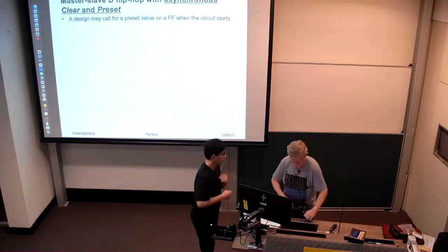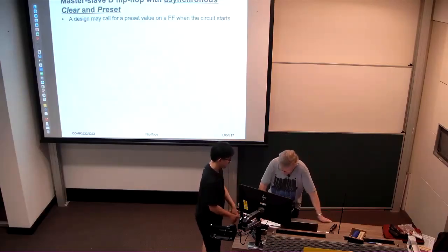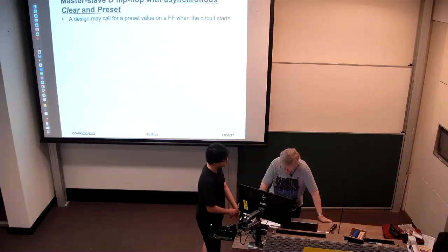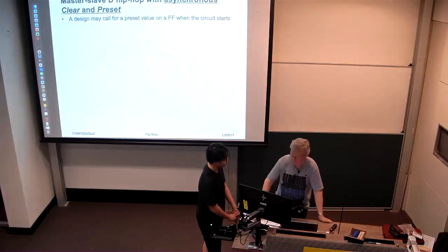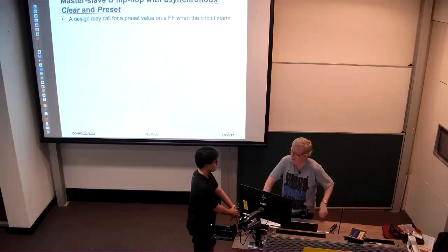One question with the lecture just now with the positive edge flip-flops. You didn't specify D in the sensitivity list, but would it matter if we do? Yes, it does, because it triggers that code if D changes and the clock hasn't had any transition, if the clock is low or if the clock is high.